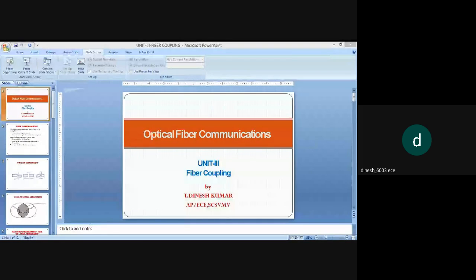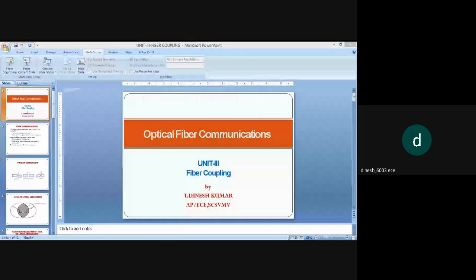So the axial or lateral misalignment in graded index fiber: in area A1, the numerical aperture of the transmitting fiber would be more than the receiving fiber. The receiving fiber will accept only that part of the transmitted power that falls within its aperture. In area A2, the numerical aperture of the receiving fiber is larger than the transmitting fiber. So the receiving fiber will accept power in this region. Depending upon this, we can choose which region to use in axial or lateral misalignments.